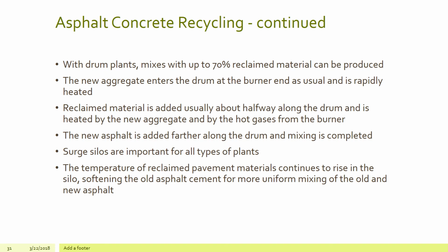Surge silos are important for all types of plants. The temperature of the reclaimed pavement materials continues to rise in the silo, softening the old asphalt cement for more uniform mixing of the old and new asphalt materials.